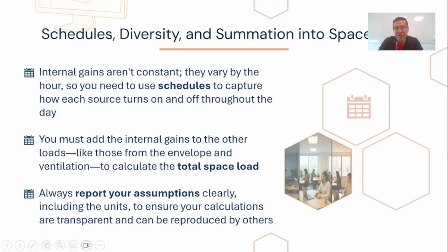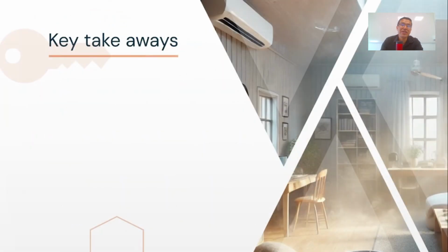Finally, always be sure to document your assumptions. This is critical for making your work transparent and defensible. You should report your assumptions for people count, lighting power density in watts per square foot, and your equipment.